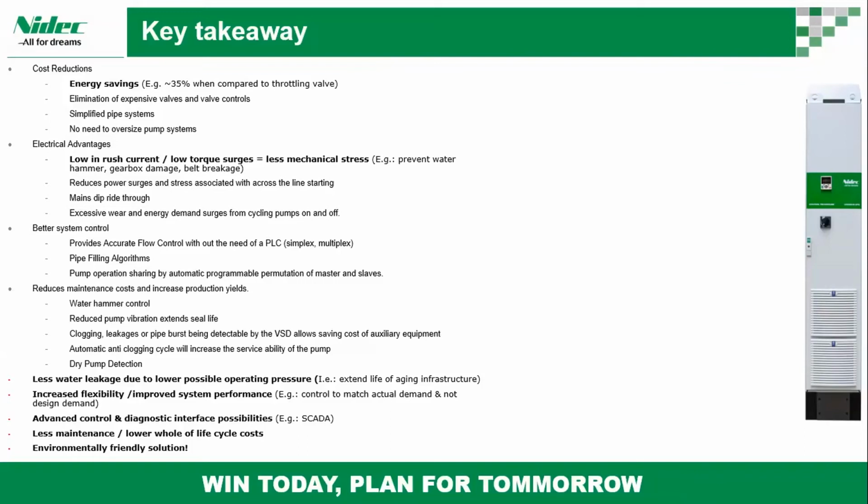And electrical advantages, again, as we said: low inrush, energy saving, and low torque surges. It has less mechanical stress and prevents water hammer, gearbox damage, and belt breakage.